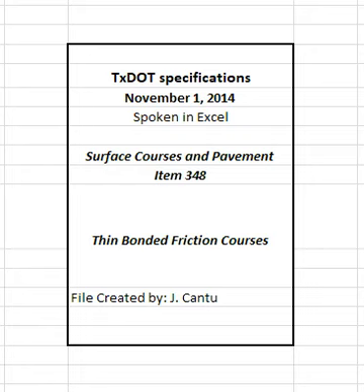3.1 Placement equipment. Provide a paver that meets all the requirements listed below. 3.1.1 Paver. Furnish a paver that will spray the membrane, apply the PFC mixture, and level the surface of the mat in a single pass. Configure the paver so that the mixture is placed no more than 5 seconds after the membrane is applied.